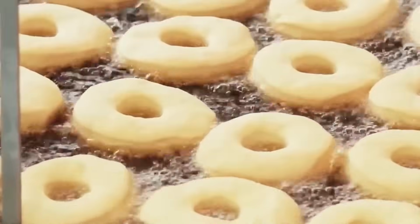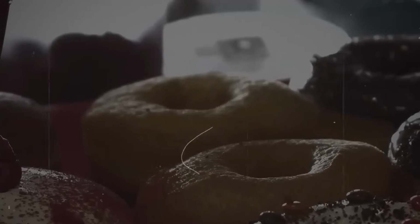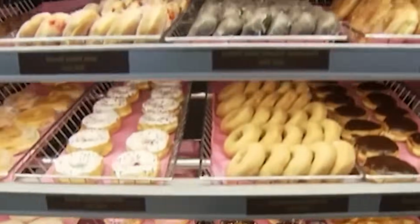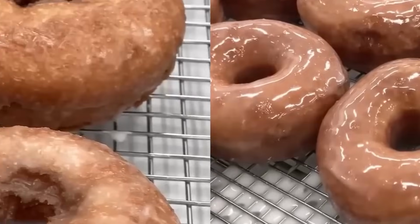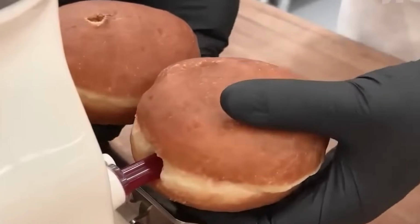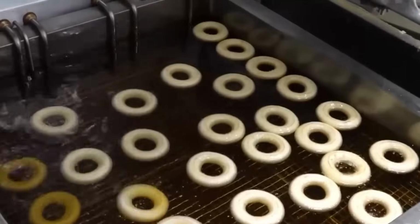Dunkin' Donuts. Donut production begins with dry ingredient blending. High-protein wheat flour, dextrose, sugar, soy flour, non-fat milk powder, salt, dough conditioners, and chemical leavening agents such as sodium bicarbonate and monocalcium phosphate are measured by weight and transferred into large-capacity industrial mixers using pneumatic conveying systems or gravity-fed hoppers.